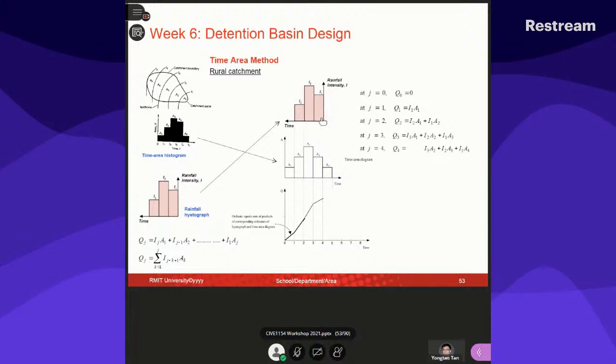For example, the rainfall lasts only 30 minutes, so after 30 minutes there will be no rainfall on A1, because the rainfall has moved to A2, A3, and A4. So A1 does not contribute to the runoff, and the contributing areas are A2, A3, A4.